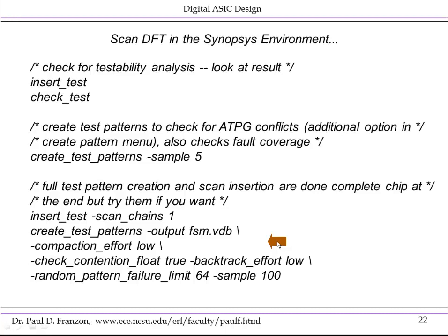For full test insertion, it's being done by the test engineer, or possibly in some companies by the designer. After design is complete, after the logic synthesis is complete, you would then go in and generate a full set of test patterns with full compaction, and they'll go into a separate file. They'll eventually be loaded into the test equipment.